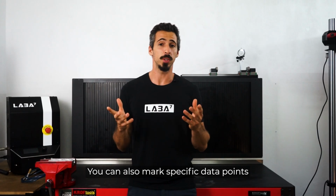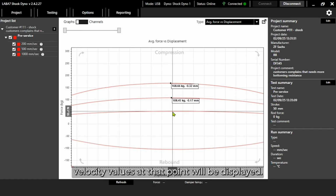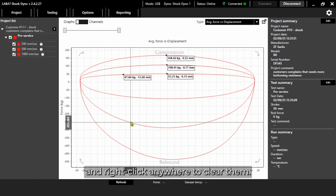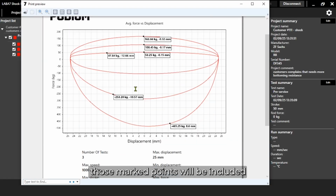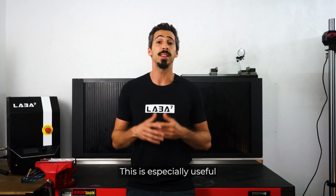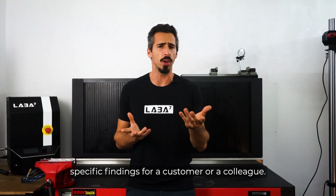You can also mark specific data points by left-clicking on a graph. The exact force and velocity values at that point will be displayed. You can place multiple markers and right-click anywhere to clear them. If you go to Reporting, then Spring, and choose Current Graph, those marked points will be included in the printed report. This is especially useful when you need to highlight specific findings for a customer or a colleague.